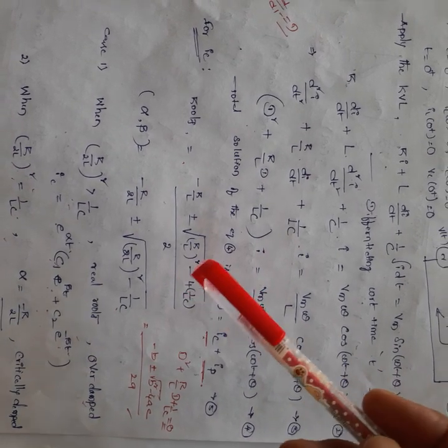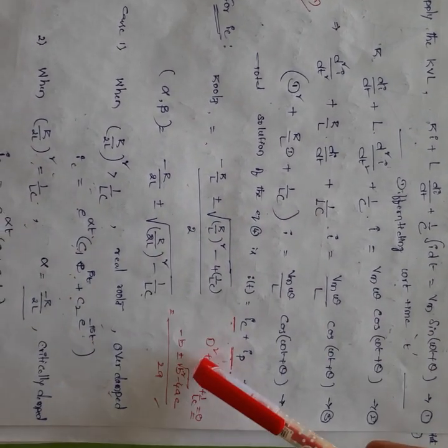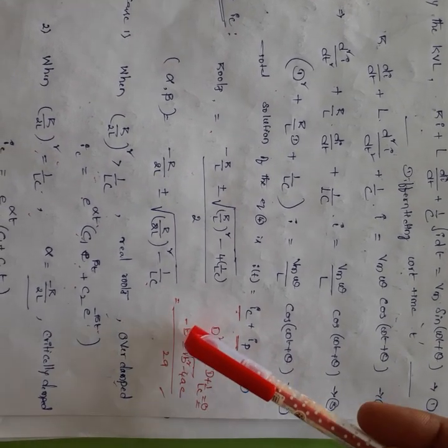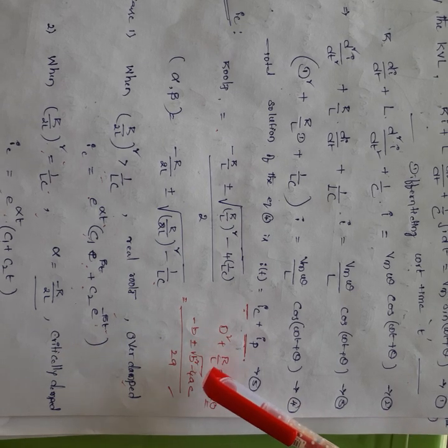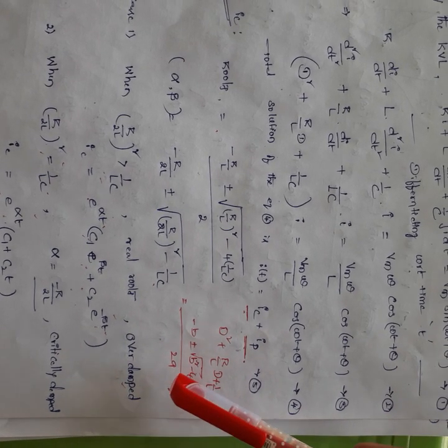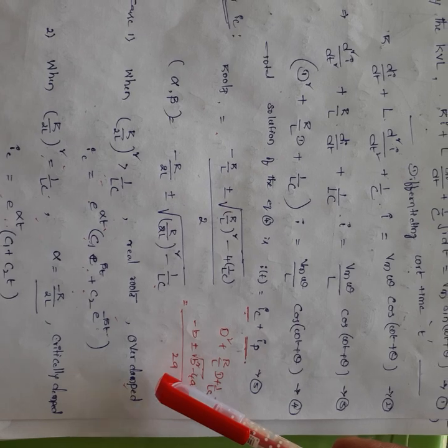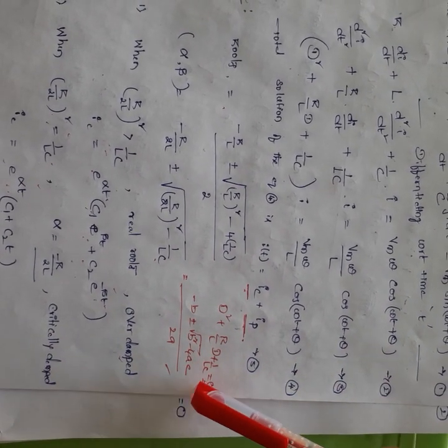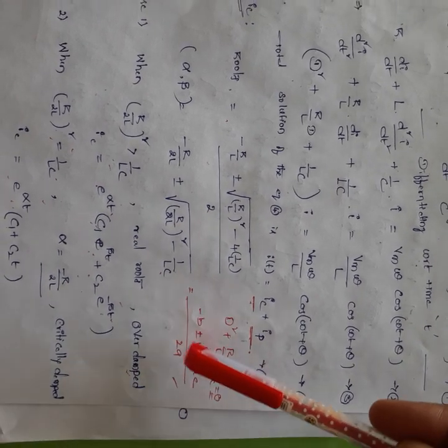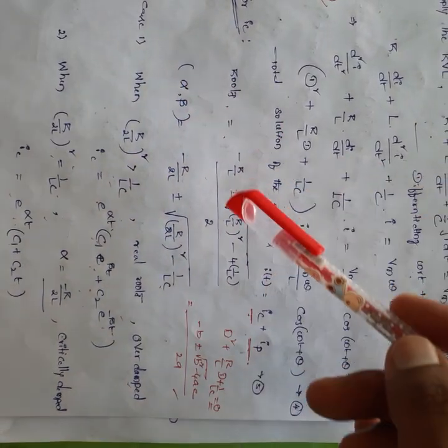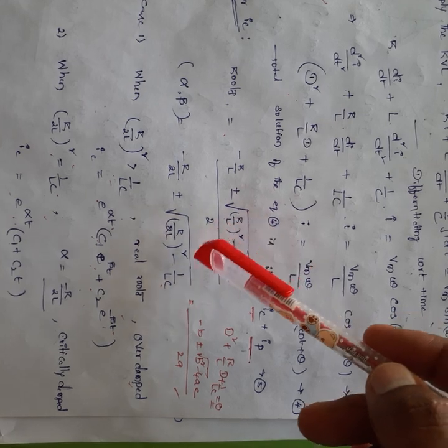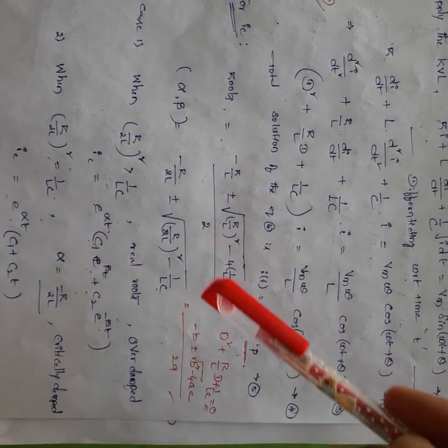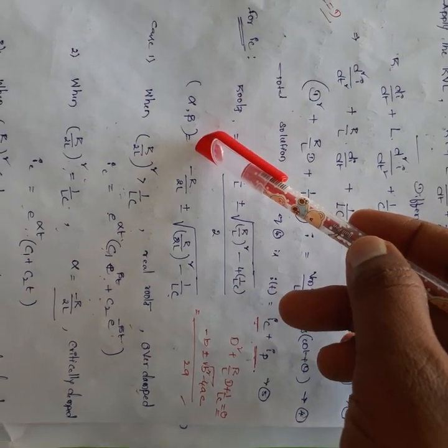First I find the roots of the equation D square plus R/L D plus 1/LC. Using the formula minus b plus or minus square root of b square minus 4ac over 2a, which gives the roots for ax square plus bx plus c equals 0, the roots are minus R/L plus or minus square root of (R/L) whole square minus 4 into 1/LC, over 2 into 1. Here alpha and beta are the roots.